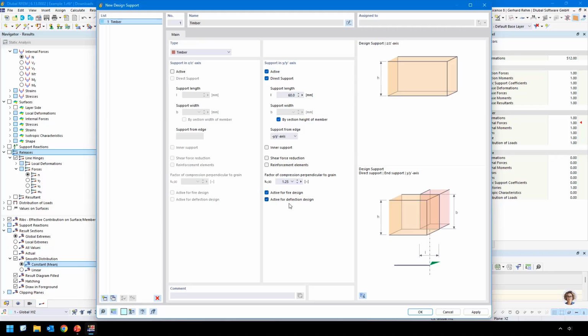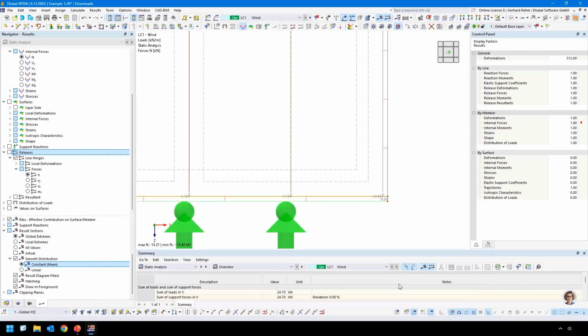In some annexes, or is it in the global Eurocode, I'm not sure, there is also an increase of KC90, or of the strength, by 20% because of the sheathing. But since our sheathing is also covering some forces, we will not apply this 20% increase of the strength. So that's it, and now I have defined this design support.